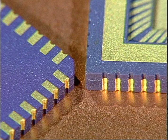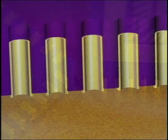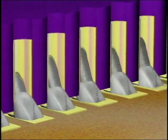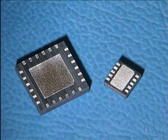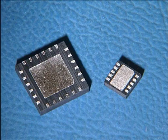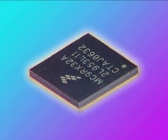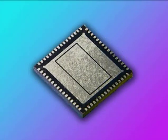Castellations are another form of leadless connection. These half-round metallized recesses in the side of the component are filled with solder when connected to the circuit board land. In addition, there are no lead components. These packages come in 2 styles: dual flat no lead, or DFN, and quad flat no lead, or QFN. Both DFNs and QFNs have terminal pads underneath the component that are soldered directly onto circuit board lands.